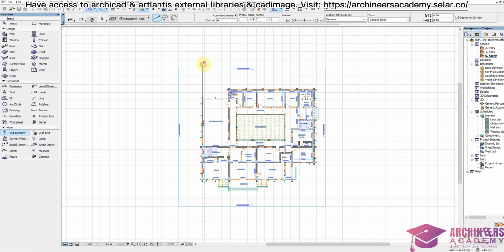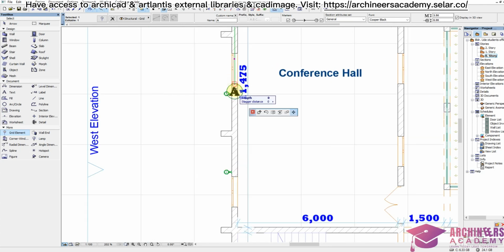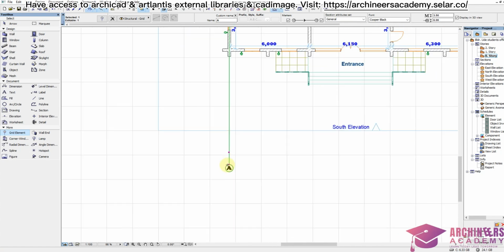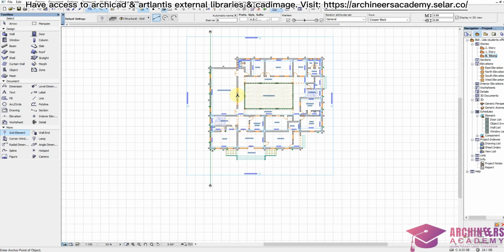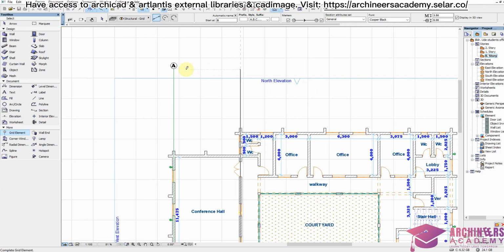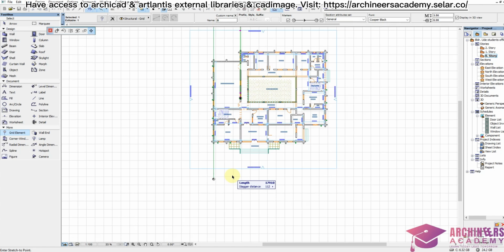I'm going to extend my grid out a bit for external dimensions. I'm creating a very good space to place my external dimensions. So I want to stretch this also. So grid AA has been placed. I move to my next wall to place grid B. This is a mark also. I can follow any of those two methods. So grid BB has been placed.